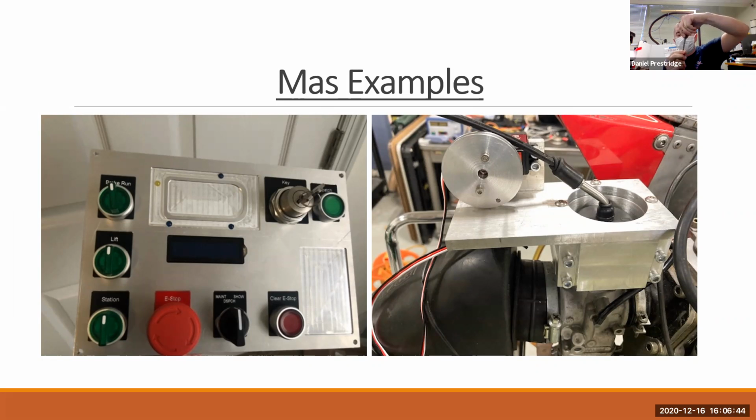And it also could have issues with it spinning non-concentric with the axis of the spindle. So if there's a way that you can maybe minimize the amount of depth, could this be shortened? Could this have been done a different way? Could you make it in a couple pieces and then put it together in some way? Those are all things that you might want to keep in mind if the goal is to have it in a certain precision, a certain accuracy at the end of the day.